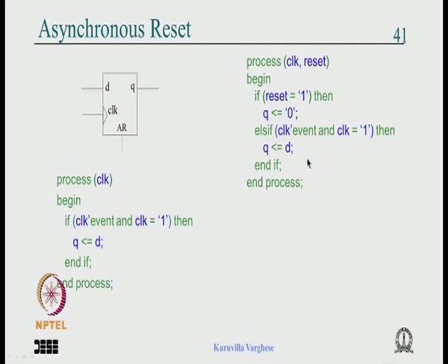There is no difference with a parallel register. You just make Q wide, with whatever width you require, and D is the same width. Then instead of 0 you write others => 0, and you get the code for registers with asynchronous reset.